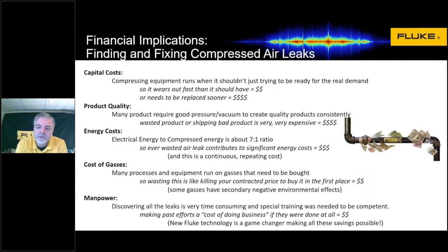If you were having leaks happen in your system, it would cause your capital equipment, the actual compressors that you have, to wear out faster because they're running more than they need to. And obviously, when they run more than they need to, they will wear out and need to be replaced sooner.